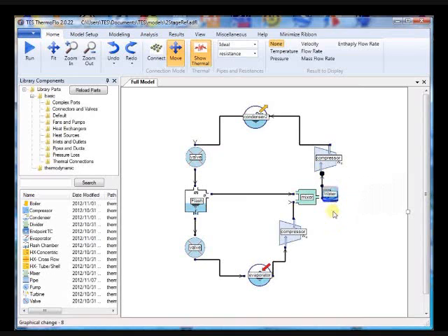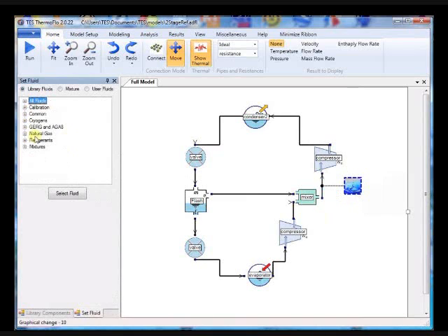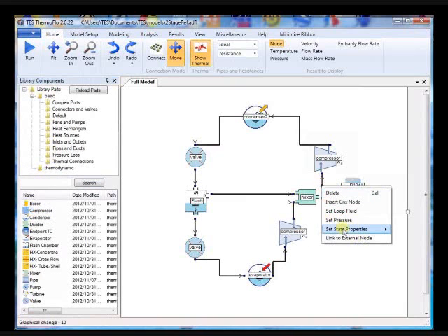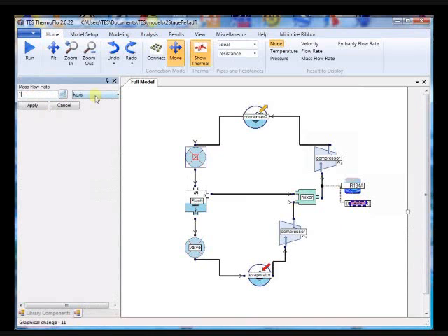By default, you get water. Here we need a refrigerant, so we double-click on it. You have all the NIST materials available. So we go to the refrigerants, and we want to pick R-134a. We pick that, and that's now our fluid. Now here's a good place to give the mass flow rate, because that's where all the flow merges. So we get a mass flow rate at that point, double-click on it, and we give it 1 so we can do per kilogram analysis.